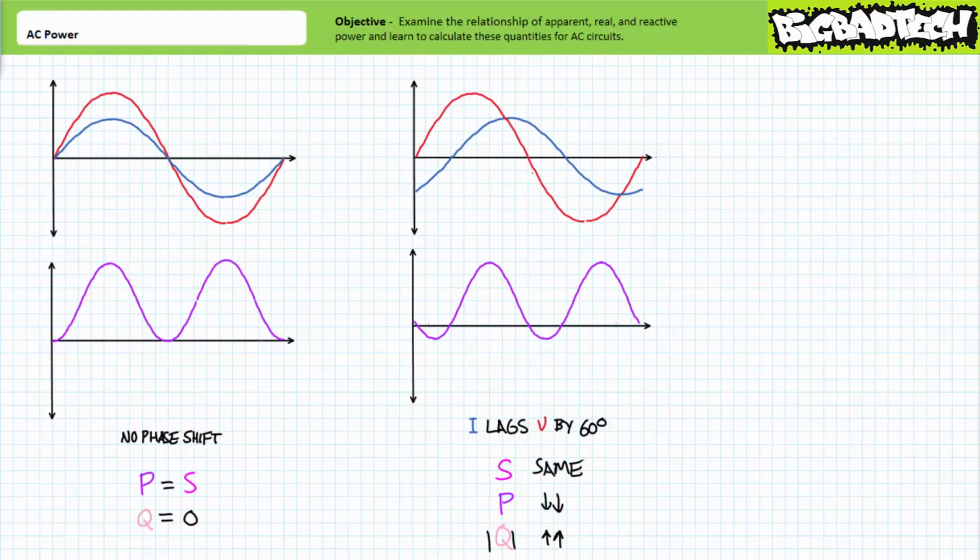Again, voltage and current magnitude remain the same, only for this occasion, current lags voltage by an increased amount of 60 degrees. This is a common scenario for elements with increased inductive natures. The plot of power shows power to exhibit the exact same shape as previously, only now it dips deeper below the horizontal axis, meaning there's a cyclical exchange of a larger amount of negative and positive power between the circuit and the source. It's probably safe to assume that real power has decreased and the magnitude of reactive power has again increased.